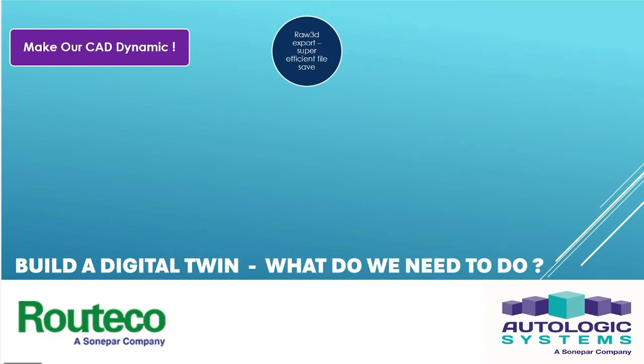We can also export from these CAD packages natively to the Emulate 3D format called Raw 3D. This is a super efficient format. It minimizes the file size. We have to handle our CAD dynamically, so it's important we are super efficient, super accurate, and super easy on the graphics cards within our hardware as we run our digital twins. We bring our CAD into Emulate 3D and we talk of adding aspects so that Emulate 3D understands what is a visual, a conveyor, a linear axis, a rotational axis, a distance sensor. These aspects are really just a list of configurable properties.